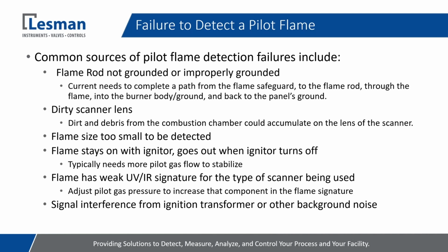So we recommend that in those types of applications that you run an extra ground wire nearby to the burner housing, just to verify that you got a good solid ground to complete that current path.